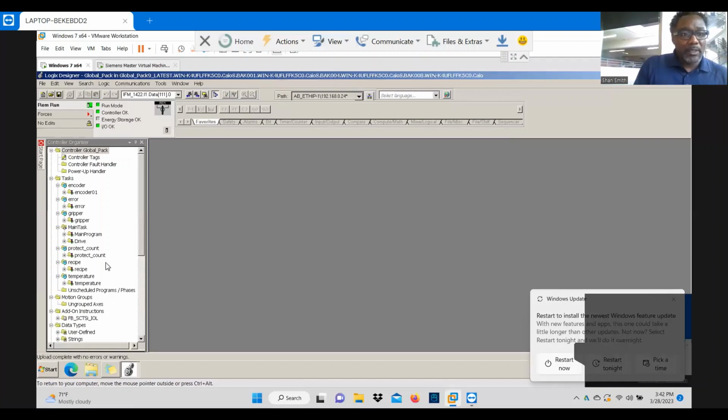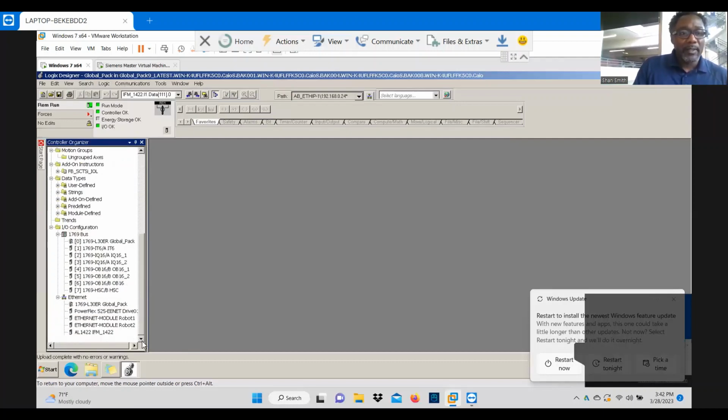So I'm going to go into one error. I know we have a test bit. Again, we are commissioning the system. We have a couple different devices on the Ethernet. We have a Global Pack machine. We have a PowerFlex drive. We have 2 FANUC Delta robots. And again, all unique IP addresses. And then I have an IFM IO-Link module. IO-Link is great, and again, it's a tool that we use. Not promoting IO-Link, it's a great tool.